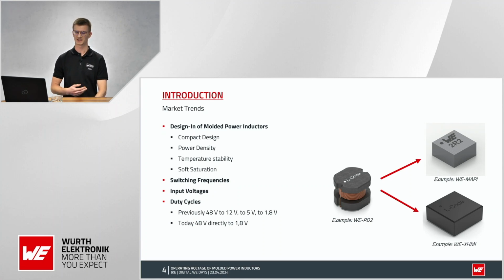But since we are getting more and more devices that are very highly efficient, we can now directly switch from 48 volts down to 1.8 volts, and this even at an efficiency of greater than 90%. And this, of course, has a big influence also on the inductors that are used in the application.